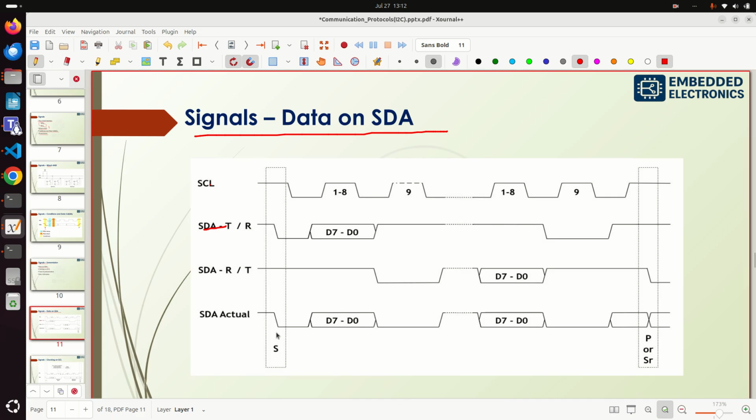And then it is passing the start condition. So how does it pass the start condition? The clock line is high and the transition from high to low happens. It is pulling the line from high to low. So the start condition is transmitted. Now master transmits the unique address and the slave receives. Next, master being the transmitter is going to transmit the seconds register address.